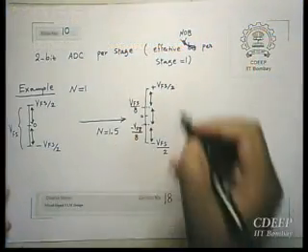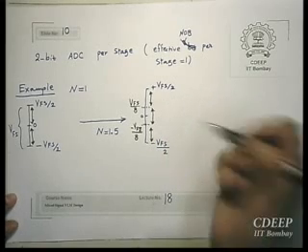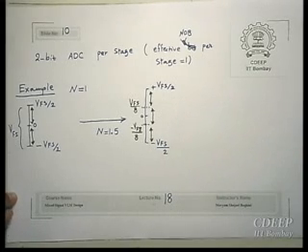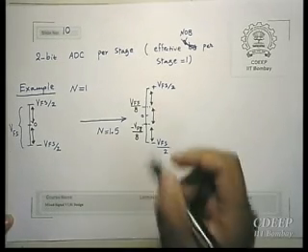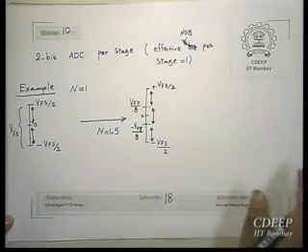I mean, that's why it is even conceptually called 1.5, because you have 2 bits but you have 3 reference levels. Means that out of these 4 possible combinations, one combination of these 2 bits is of no use practically. So you are adding redundancy, but now you are predicting, or in fact calculating, your residue more accurately. Okay. So now what are the actual sizes of these values?